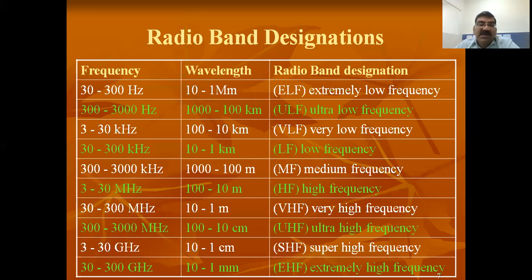So for 30 to 300 gigahertz, we don't have anything. For 3 to 30 gigahertz, we have something: whatever vector network analyzer we have, it goes up to 14 gigahertz, from about 300 kilohertz to 14 gigahertz. So we can measure this frequency range. We have that at the institute. It is a very costly instrument, but fortunately we have it.